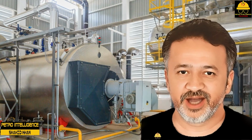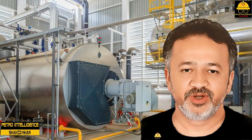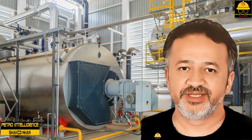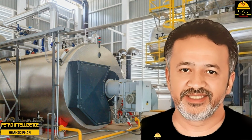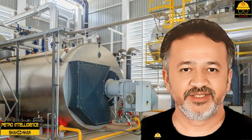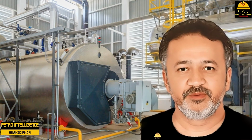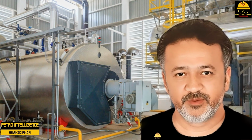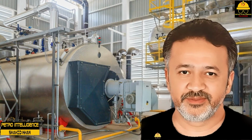Let us discuss now steam. As long as steam and water are in contact with each other, the steam is saturated. This saturated condition means that, for every temperature of water, a corresponding pressure of steam exists. The pressure on the water sets the temperature as long as the steam and water are in contact. Basic boiler design removes the steam from the upper steam water drum and heats it up at essentially the same pressure. This process is referred to as superheating.